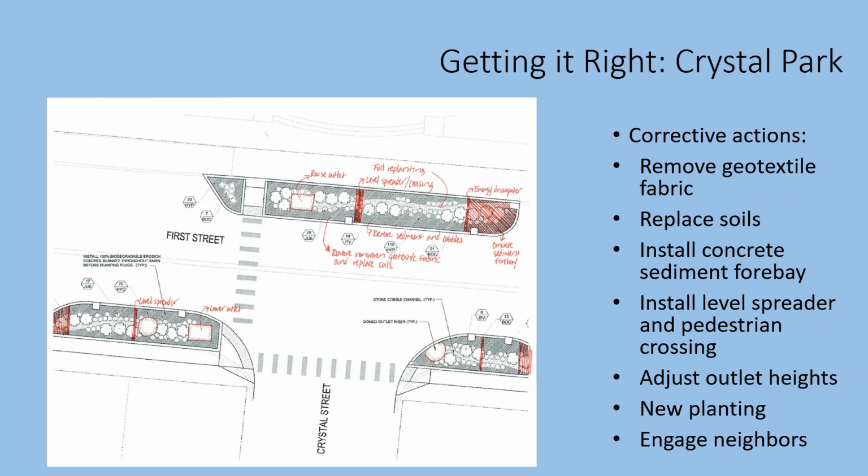What we're finding is actually that they're functioning a lot better in terms of both plant health and stormwater management by eliminating those low flow channels, which were basically acting as small little bypass channels. Next slide.